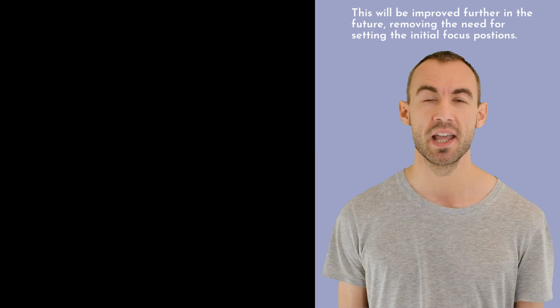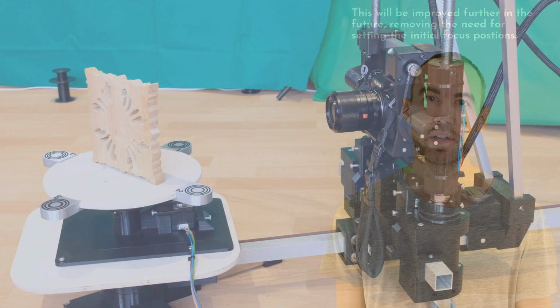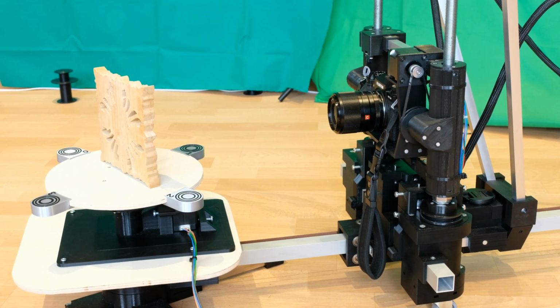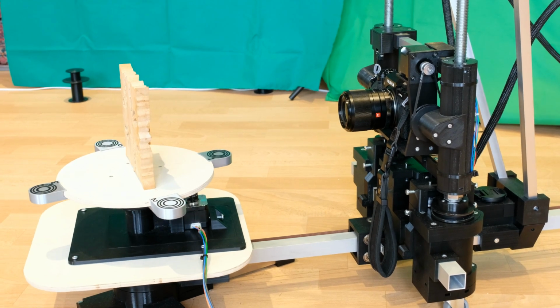Talking about 3D reconstructions, let me take a little bit of time to show you what I do in my setup to deal with focus stacking. First of all, I'm not using the focus bracketing feature that's built into the camera. My machine controls the camera directly and it automatically sets the focus positions. What I need to do right now is to set a minimum focus position and a maximum focus position once before the machine starts. And then for each physical location from which photos are taken, it automatically takes the necessary photos at different focus positions.